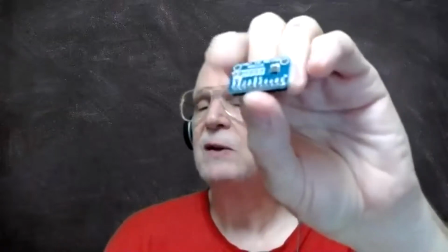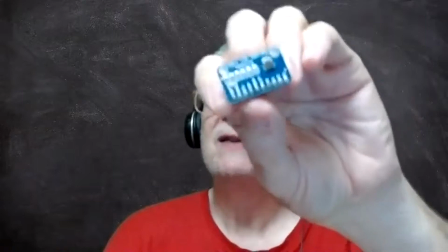So what I did was I finally got some fingernail polish remover. I took my Q-tip and rubbed it on the top of the chip. And sure enough, the silk screen number that was on there did rub off. I'm down to the point I can almost see something on there, but it looks like they sanded the chip first. But I could faintly see the original numbers. So that's what I was doing when we started the meeting, because I think it's a valid part. It's just that they put the cheaper 12-bit part on and remarked it as a 16-bit part so they could sell it for twice the price.